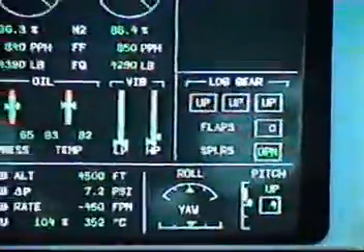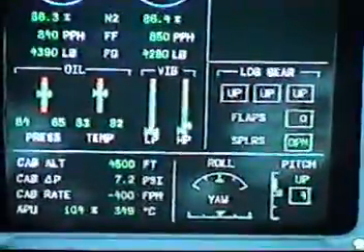Deploying speed brakes at high speeds induces a pitch-down tendency. The pilot force to counteract this tendency is 9 kilograms or less when Mach is 0.85. Higher counteracting forces may be required at higher Mach numbers. Therefore, using speed brakes will make you also pull back the elevator.